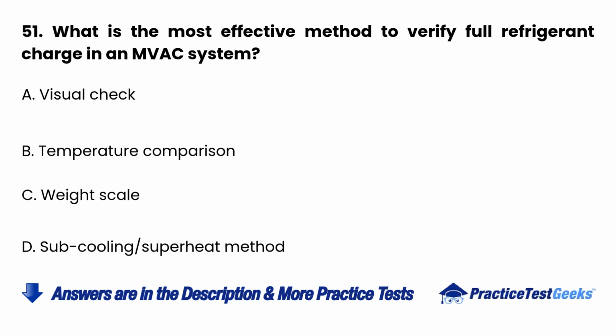51. What is the most effective method to verify full refrigerant charge in an MVAC system? A. Visual check. B. Temperature comparison. C. Weight scale. D. Subcooling superheat method.